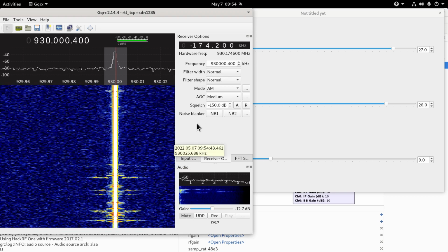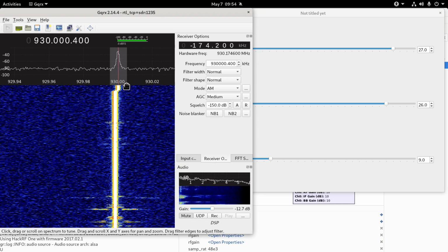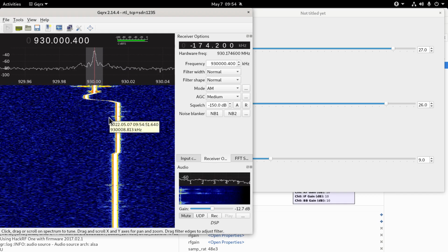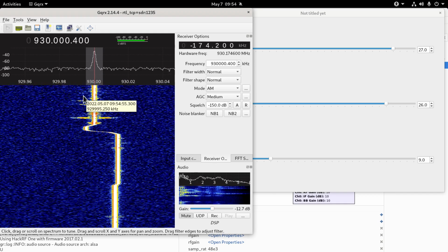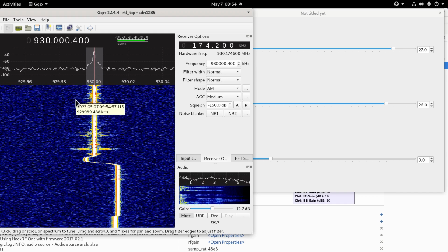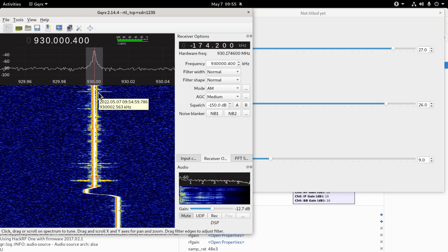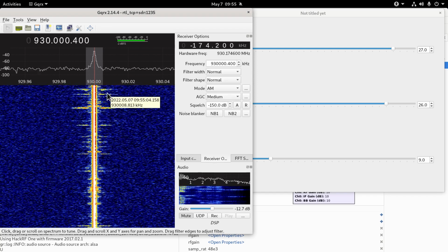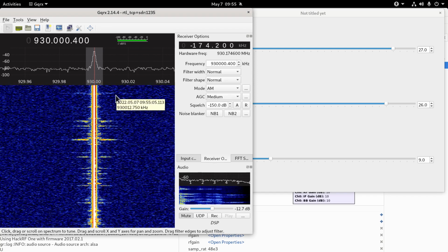You saw what happened though. I'll just keep speaking while it's doing it. We have the carrier in the middle there, which is what you expect, and that's what you tune into when you lock into stuff. But you can see it modulating from side to side. And as I said before, the higher the frequency that's mixed with it, the further out from that center frequency it'll be.